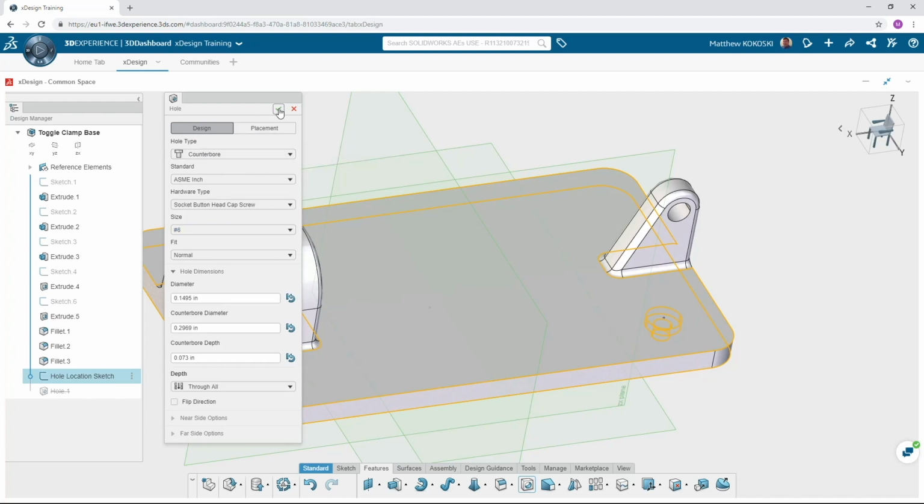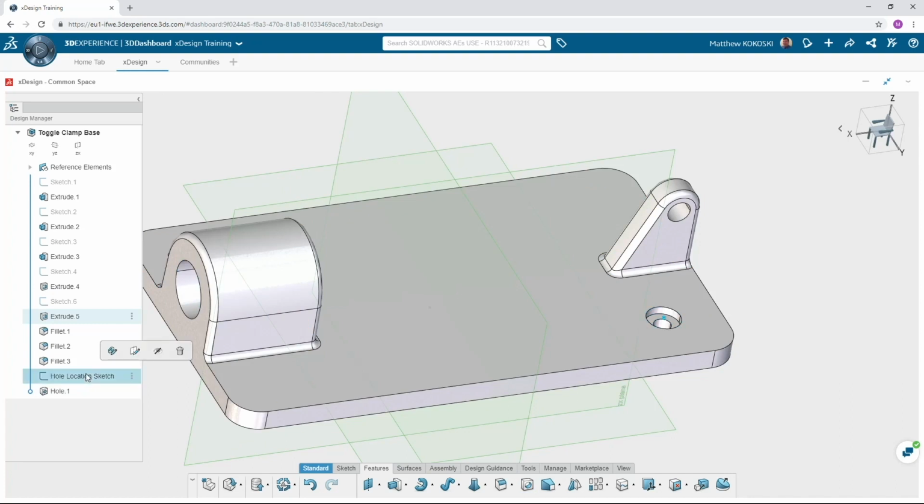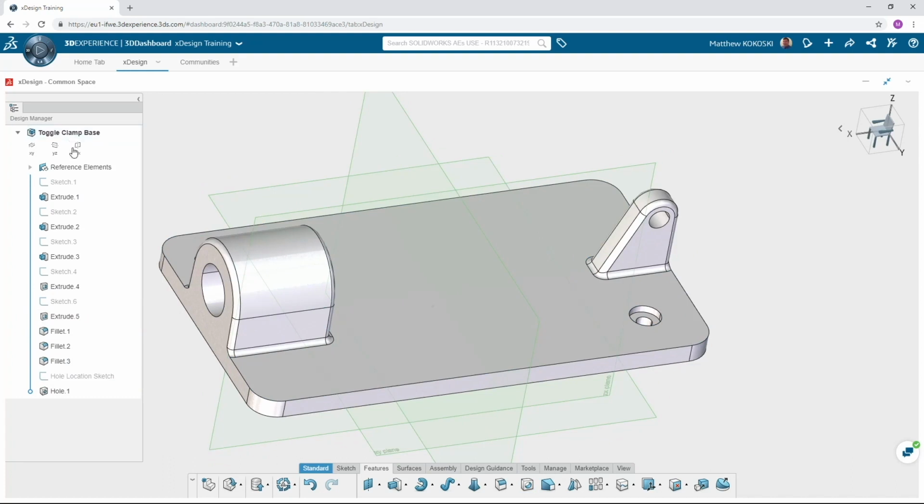We no longer need to see the center point. Clicking on the sketch and then selecting the Hide command will turn the visibility of the sketch off. The same can be done for the 3 default planes. This won't stop us from being able to use the geometry, but just shuts them off from our view.